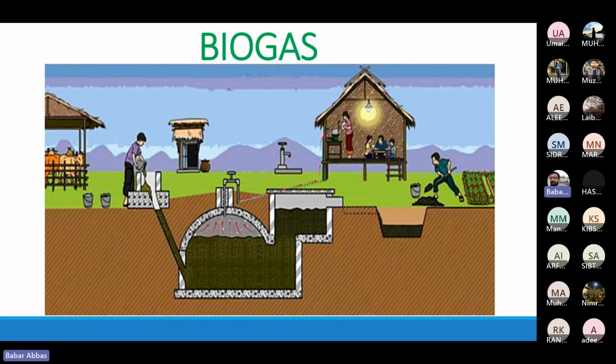Initially, we had waste, and now it has been converted by the use of this technique into two useful products. One is the biogas, which can be utilized for various domestic purposes, like it can be utilized in heating up the homes, it can be utilized to lighten up the homes, it can be utilized to cook the food. And the other product which came from this unit was a slurry or semi-solid type material, which is a stabilized material and can be utilized as biofertilizer for the horticultural activities.